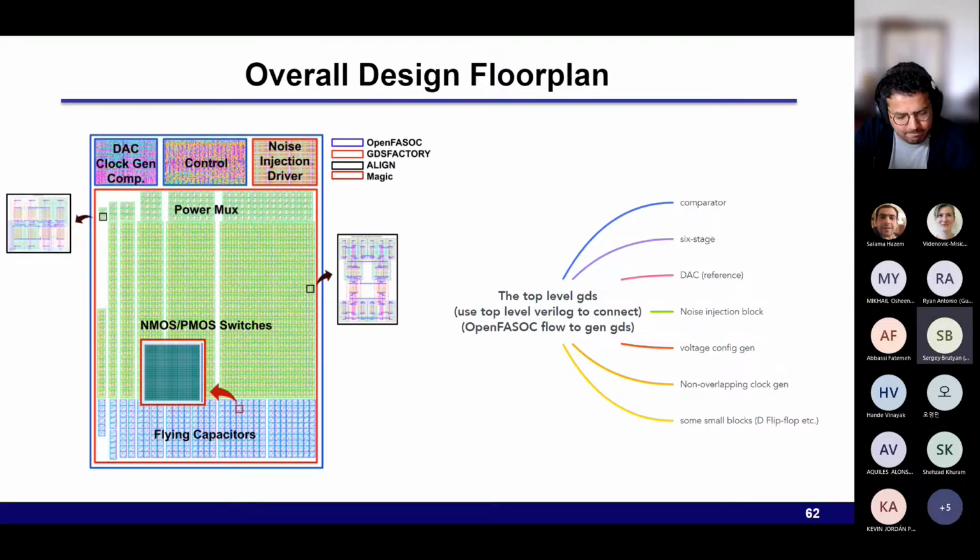Okay, and another question is about the open source toolchain. I heard that we have some missing point which has only Siemens EDA. The open source alternative of that tool doesn't exist. But what is exactly, I mean, the name? Maybe you heard or know about that tool, because there is OpenLane, which is based on Yosys and also generates the GDS files, I mean the RTL synthesis and so on. But what are we missing, what holes do we have in the open source toolchain flow?